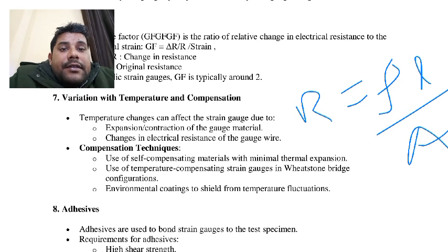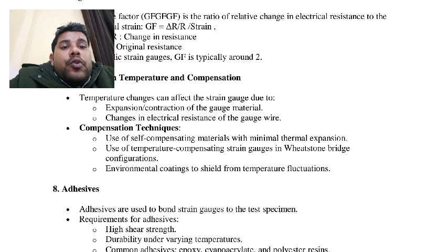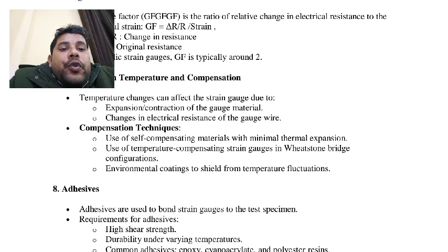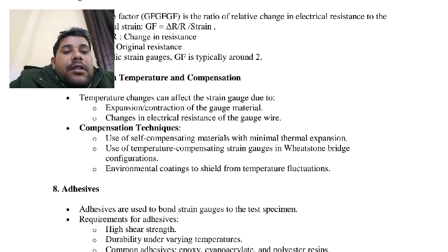Second, compensation technique: self-compensation using material with minimal expansion. Use a temperature compensation strain gauge with a Wheatstone bridge configuration.